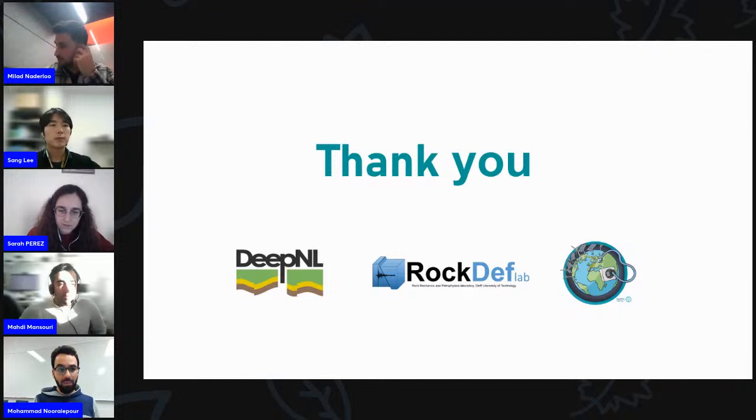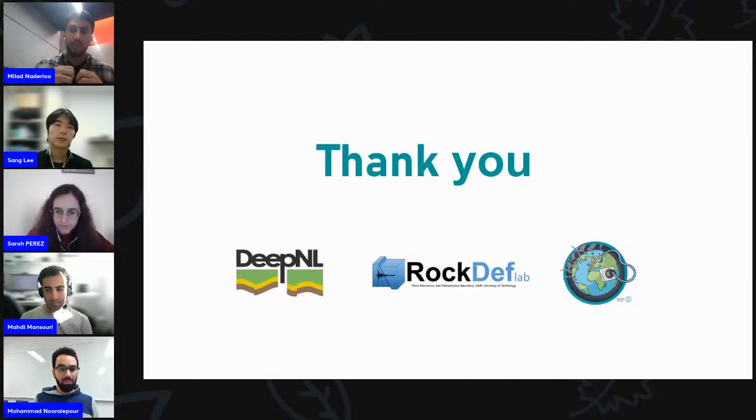Yeah, unfortunately we didn't do that, but similar work was done at Utrecht University. What I have seen is they did cyclicity in the elastic zone, not bringing the sample to failure, just in the elastic zone, and they saw what the main mechanism is: you have your quartz grains in sandstone, and between them clay coating them, and this squeezing of the clay is the main mechanism. And then they saw in CT how microcrack density changed before and after exposing to cyclic loading. But we didn't do CT. Okay, thank you very much.